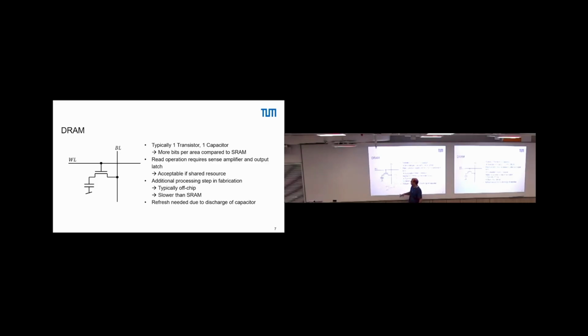So what we need is that we also refresh this value. And refreshing this value happens because we have a driver implemented as a sense amplifier that amplifies back to VDD. So virtually we now put a lot of positive charges here by the sense amplifier. Maybe I should write them in orange.